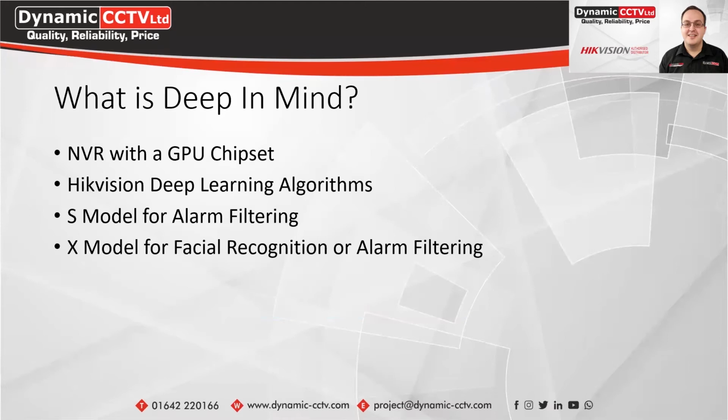So with the DeepinMind MVRs, they're an MVR with a GPU chipset which runs the DeepinMind algorithms. And there's two main kinds for these DeepinMind series. You've got the S model, which is specifically for alarm filtering. So this is done on intrusion detection or line crossing. If you've used standard VCAs before, you know that any animals or bushes, etc. can trigger the line crossing or the intrusion detection.